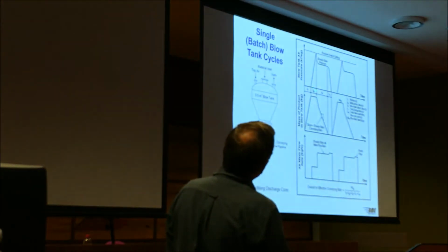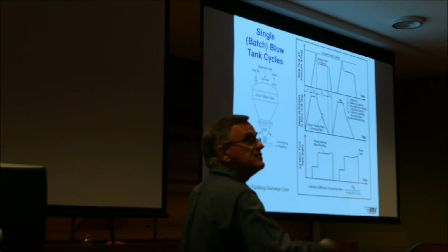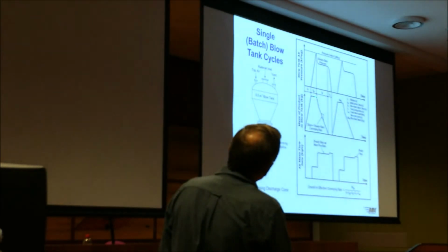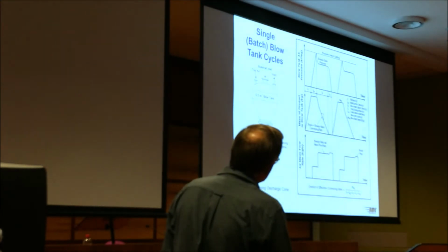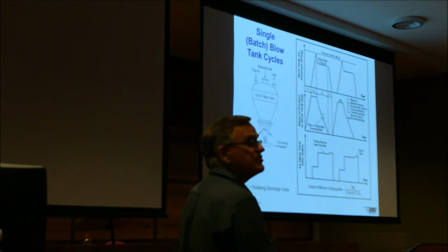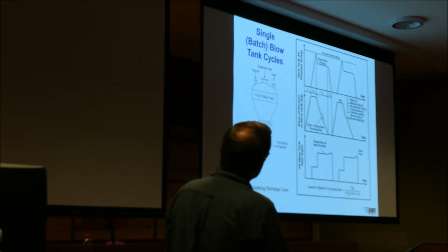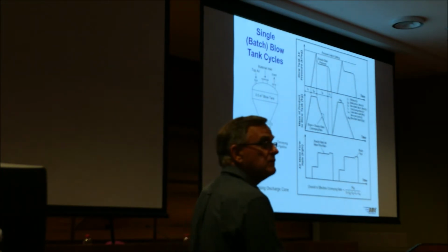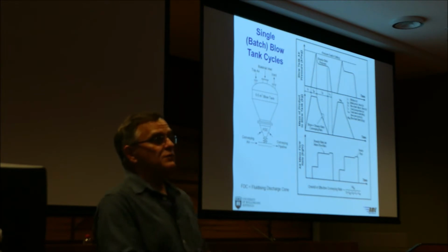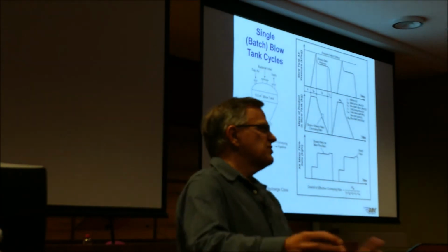TIP is initial pressurization time, that would be 20 seconds, 30 seconds, whatever it is. The time taken to discharge is from that point to that point, when it's empty. The time to vent or purge the system, which is this time here. And once you're back to zero pressure, at that point there, we can restart the cycle. And we need to add on another 10 or 20 seconds for valve switching. We do that per cycle.